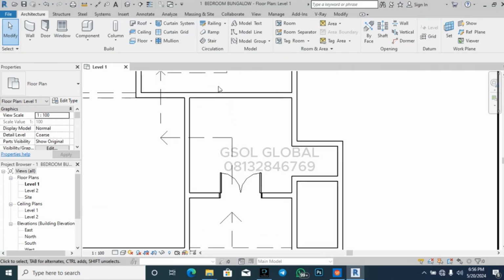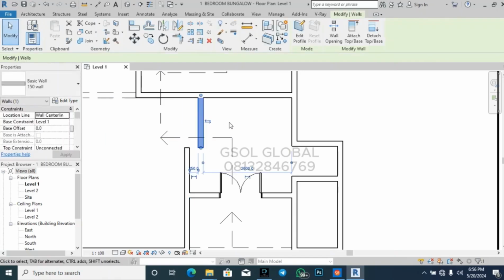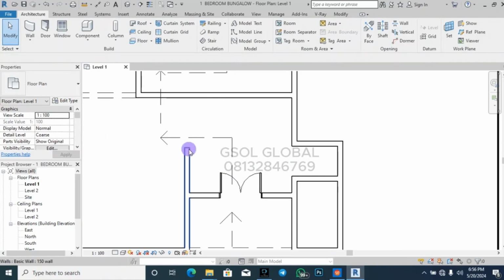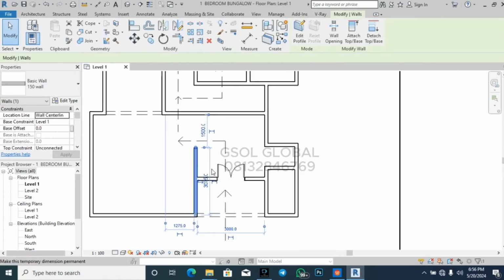Remember? So now the next place we're going to be opening is this place. So remember, you're thinking about cost. Should I put a door here? Should I not? Nope. You don't need to put any door in that place. What you just do is to create an opening. I already placed a well secured door in this place, so I don't need to put a door here again. So I'm just going to use my split tool and then delete the part that I want to delete. All right. So I delete this part and then I'll check my dimensions if they are intact.